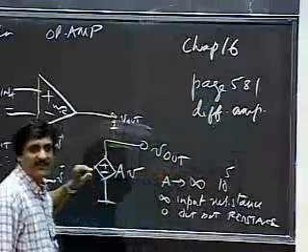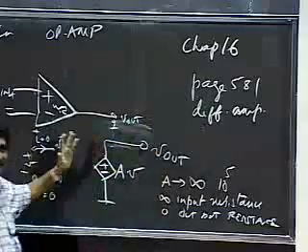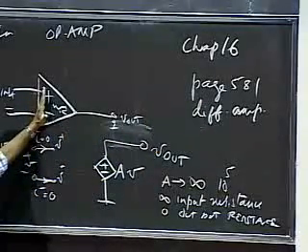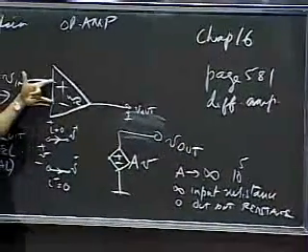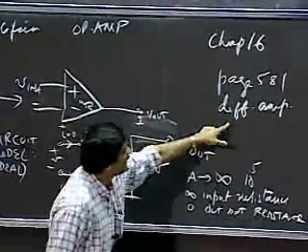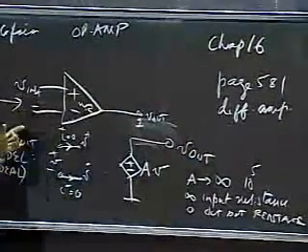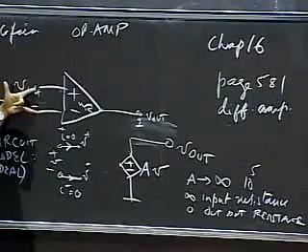That differential amplifier that's solved in that example is usually the first stage in an operational amplifier circuit, at the input. And that differential amplifier, as the name implies, amplifies not a single voltage, but a differential voltage.